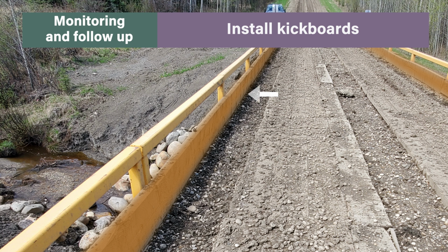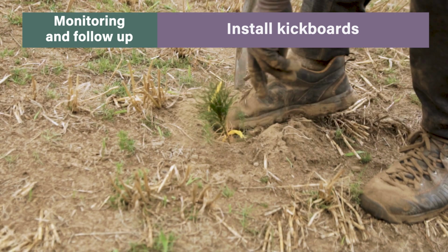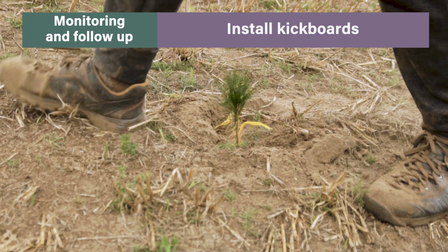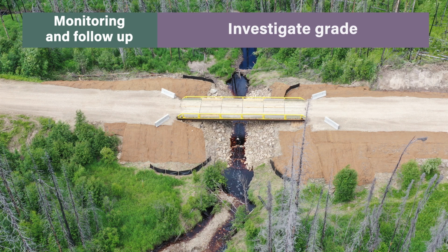As you can see, this site has exposed soil and bank erosion. Erosion control and establishment of ground cover is required to prevent sediment from entering the watercourse. Investigate how the road is being graded and ensure road approaches are being graded away from the bridge. This helps direct any sediments away from the watercourse.